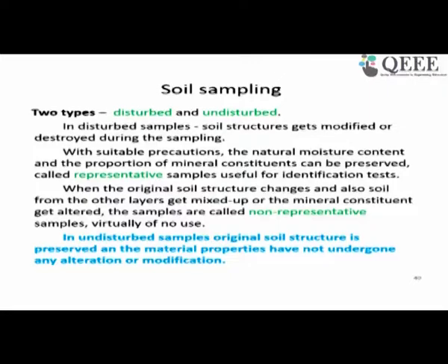When the original soil structure changes and also the soil from other layers gets mixed up, it is called a non-representative sample. For example, in cases of wash boring, where you completely mix up the soil, your soil is of no use, that is non-representative.